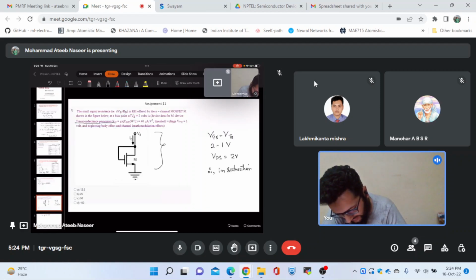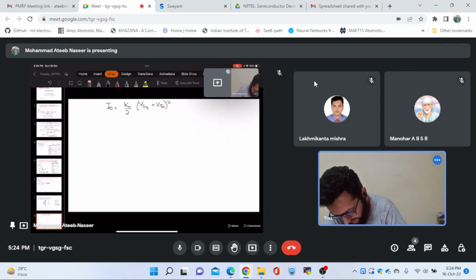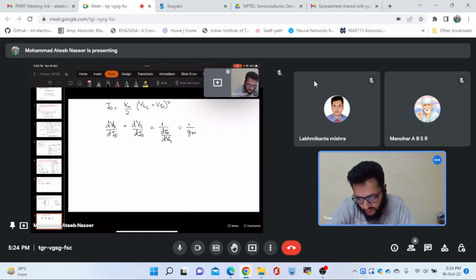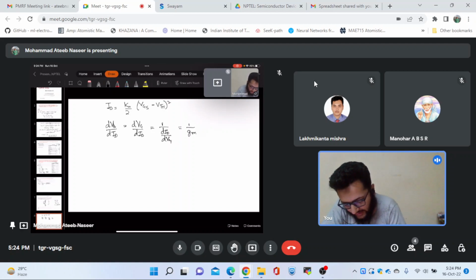We were required to find dVD by dID, and this dVD is simply dVG by dID, or equal to 1 by dID by dVG, and this is simply equal to 1 by gm, as we all know dID by dVG is gm. Since this source is grounded, this VGS will be VG.